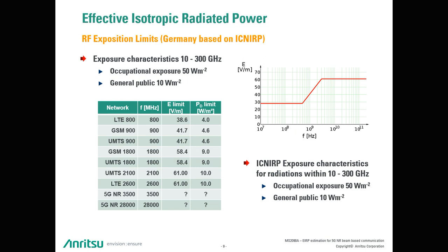So, while a base station in classic GSM mode and maximum 20 watts transmit power never exceeds 20 watts, a UMTS base station also with 20 watt RMS power peaks up to 200 watts, or 400 watts with 13 dB crest factor. In addition, the number of used transmission channels multiplies the radiated power accordingly.